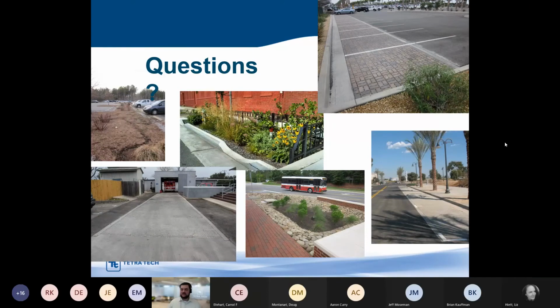Those are interesting conversations. If you look at some of the standard details that are out there, particularly Philadelphia, which obviously has extensive standard details, and a lot of other communities do as well, generally I'm going to put some kind of liner between the BMP and the road. In the discussions I've had, if you put a liner down about 3 feet, that should prevent any lateral movement of water to a depth that would impact the subgrade. So if the soils are wetted 3 feet below the subgrade, then it shouldn't impact the road. That's generally what you'll see.